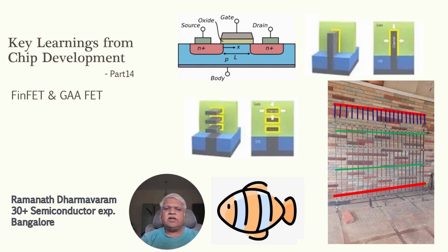So here I will be slightly digressing from the RTL to GDS topic and giving some information on FinFET and why it has been developed. This was developed at the University of California, Berkeley, and was first deployed in the product Samsung Galaxy S6 in 14 nanometer. The three-dimensional FinFET geometry is a key technology inflection that enables chip makers to continue shrinking dimensions and packing more and more components onto a chip.